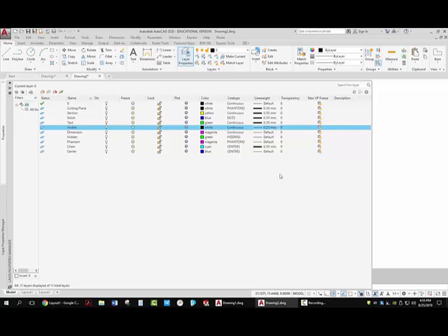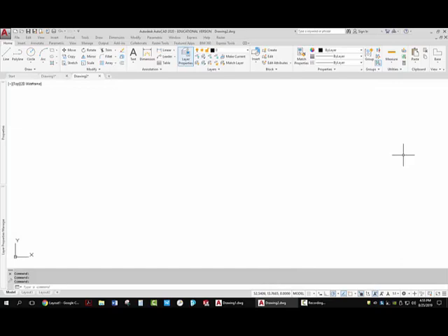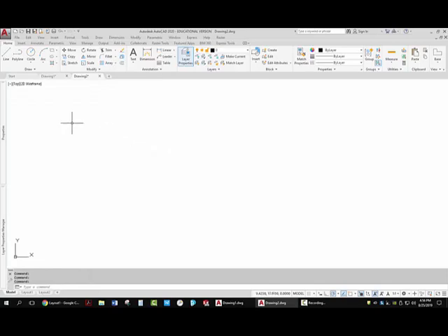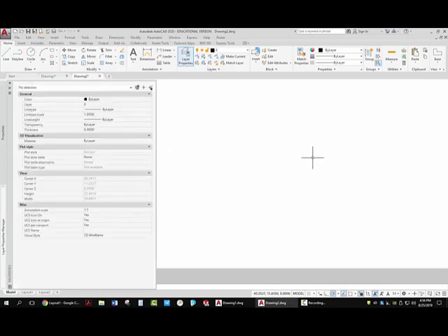Once those are all done, all you have to do is move your mouse off to one side, and the properties palette will close as long as you've gone to the properties of the palette and indicated you want it to be anchored left or anchored right, and that you want it to be allowed to dock. Docking simply means when you come off of it, you wait a few seconds, it'll go back over here, and now it'll come out, it'll go back.